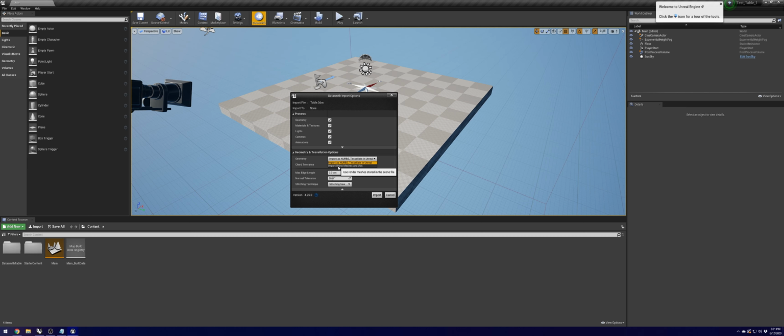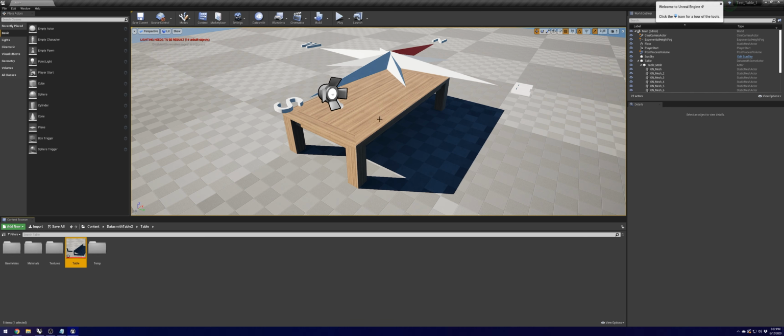If you didn't do that and you just imported your NURB geometry, then you would want to import it as NURBs, and Unreal Engine will tessellate it, basically trying to create a mesh as realistic as possible to your NURBs model. The issue with that, like I mentioned before, is that all of your UV mapping gets deleted. So when we click import Rhino meshes and UVs, it brings in our meshes and the UVs that we created. Now we can hit import. So now you can see